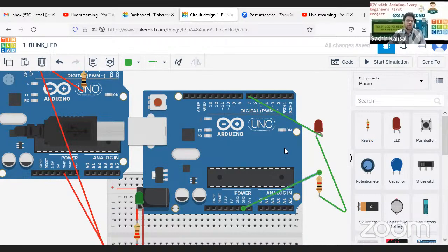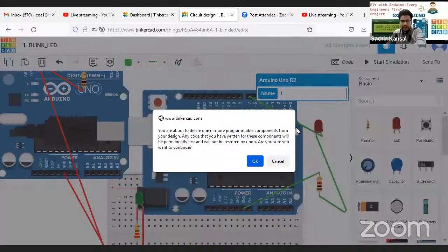It means if you want to connect any system to the Arduino, you need to specify two things. First, where the individual component is connected. Second, from where you are giving the input. Either you are selecting 5 volts or you are selecting 3.3 volts. Based on these parameters, we need to understand how you can perform the actions. Okay, so let us do that also.